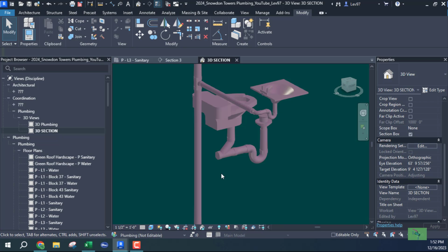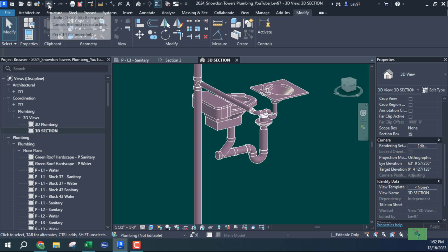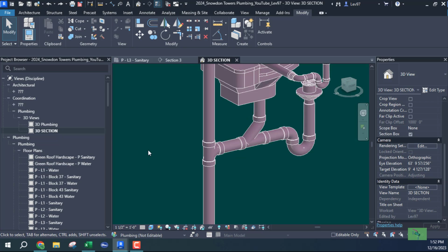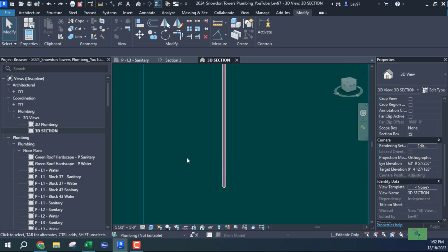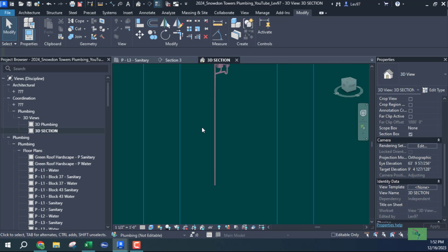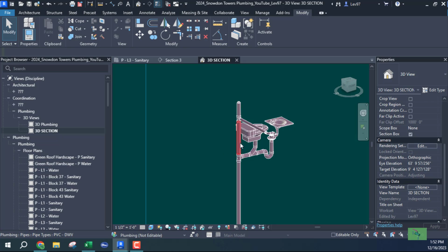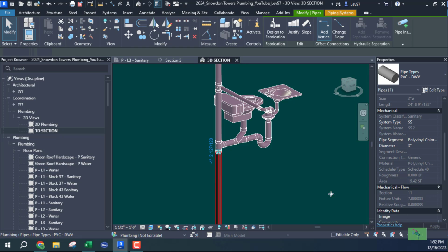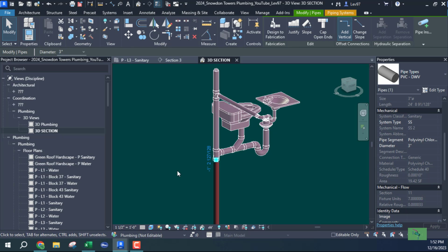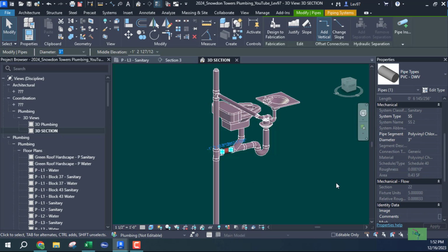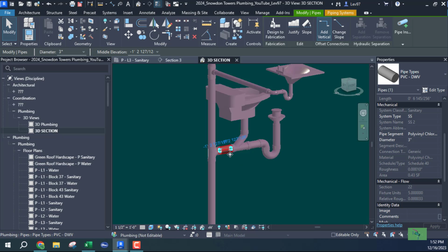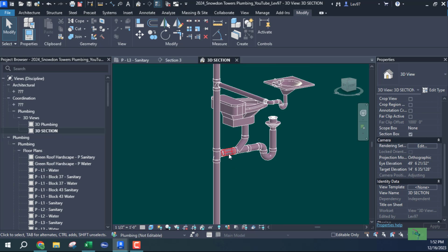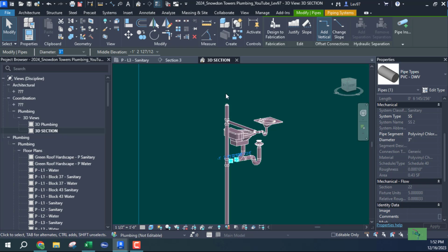Okay. Let me back up, and come down and erase this guy. Okay, I'm going to erase that, and this should say 2 fixture units here. Okay, it should say 7 here. It should. Oh, it does. Okay, so that's why I wasn't getting the number that I want. This should be 5. Okay. But I think it looks good now because the number of fixtures aren't that critical.